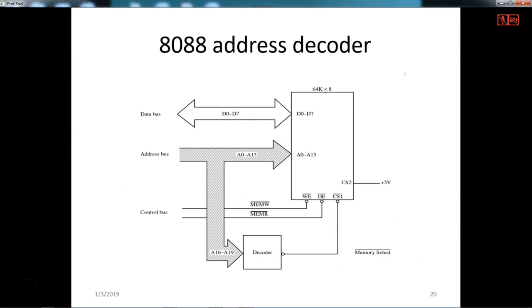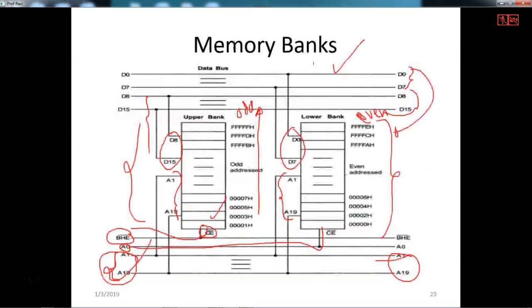So then to design a commercial system, what they did is they brought one more processor called 8088, which has only 8 data lines. That means only one memory is needed to design a system, but system performance is slow. Right. So now one such system I am showing here, which is how to design a decoder in between. See here, in this case directly A1 to A19 we connected to A1 to A19, but like that particular RAM should be connected to 2000H.